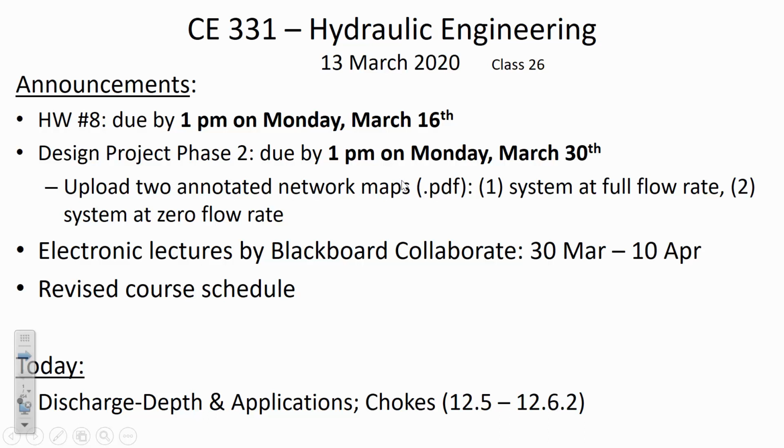Normally I would have had them graded by now, but redesigning the semester for 3 classes has slowed me down a little bit. So I think next week's going to be quite a lot quieter. I'll probably be able to give it to you next week, hopefully the beginning of next week, and then that would give you about 10 days to update your flow rates. But if you don't have your updated flow rates in time for the network sizing, you can always, in your final submission, further optimize your pipe network. If you lay out where the pipes are and get an initial sizing done on your beginning estimate of the flow rates, you can update that later.